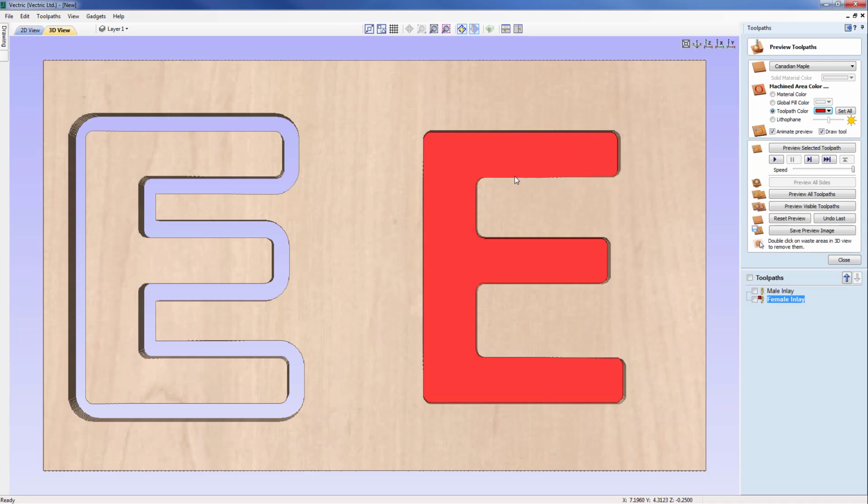Similarly, in this area here where the tool was going round the inside of the female, we were able to originally generate a sharp corner there, but that's been purposely rounded off because we cannot generate the same sharp corner on the male. So the two have been matched. Both sets of vectors have been modified.